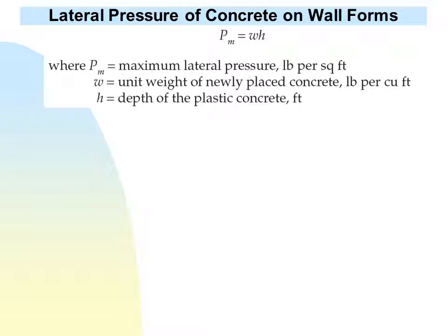If concrete is fluid, if you deal with it as a fluid, then the pressure that it will be acting on the formwork would be simply the unit weight multiplied by the height, hydrostatic pressure. So this is simply the pressure. It's linearly increasing from 0 until reaching a value of W times H, or gamma H. However, this is the most extreme situation. But if it is a solid, it will be something very much less than that.